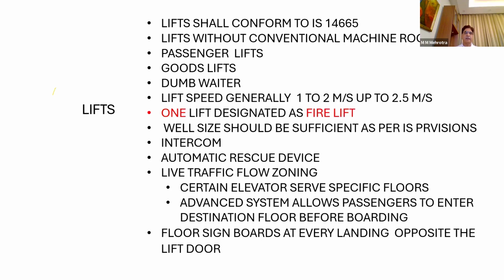Now I am using that lift during that time. I get trapped here. So there is an ARD, automatic rescue device, where from the battery bank, it provides supply to the brake for a short time.